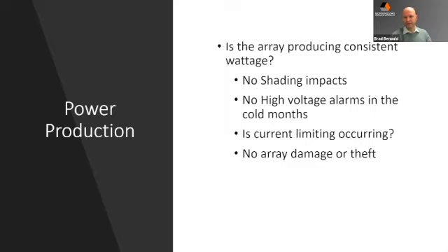And then when you get that year over year view long term, you can start to get an idea of the maintenance of the site, because batteries have a long life. Lithium has an even longer life, but they do degrade, and it is something that will have to be replaced over time. And when that occurs, you want to be able to predict when that's happening, because maintenance at the site is expensive, and having that predictability, or even better, predicting when a site is ripe for a replacement of the battery before the load goes down.